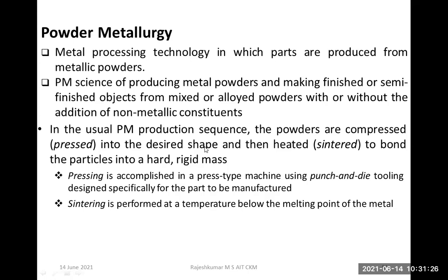it is a sequence in which the powder is first compressed or pressed and then taken into the desired shape, and finally it is heated. Heated means sintering, to bond the particles into a hard and rigid mass. So this is the process. Powder metallurgy has a vast history, and with that history, nowadays let us consider different examples with respect to powder metallurgy,